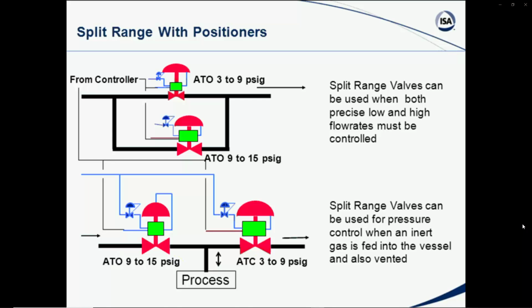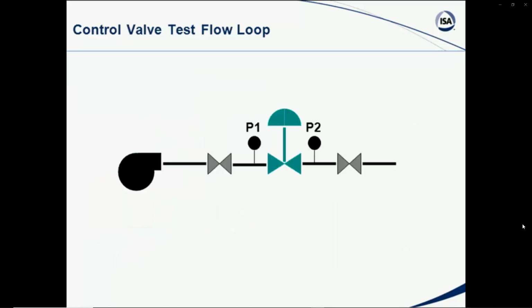But you can do that mechanically, if you will, by using valve positioners. Valve positioners are very handy in some cases when you have a large valve, high pressure drops, maybe you have mechanical stickage and this kind of thing. Valve positioners can be very handy, very useful for this type of situation.